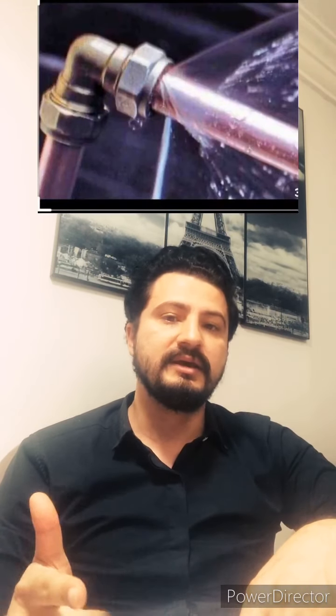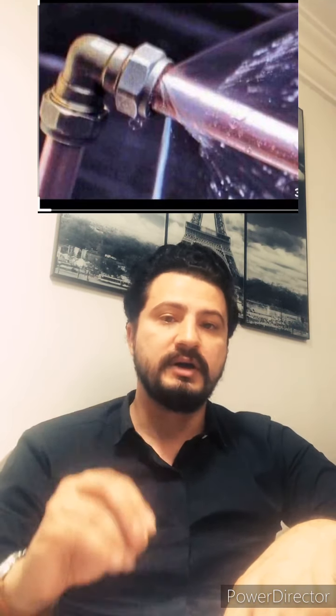And the control line is still working, no plug, no leaking in the control line. In this case, we can lock open the tubing retrievable safety valve to insert a wireline retrievable safety valve, which is the secondary type. So that is the secondary type of wireline retrievable safety valve.